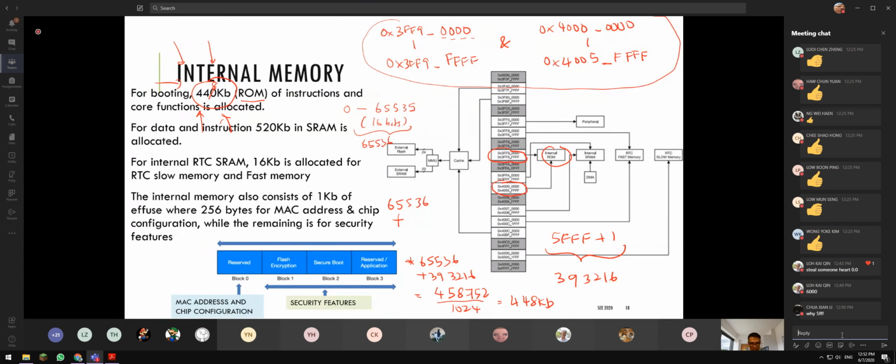Sleeping deeply doesn't mean that you are dying, or that your microprocessor is not functioning. Let's say, for example, you are sleeping at night. If you're in deep sleep, don't tell me that your brain is malfunctioning. During sleep mode, the real-time clock is still running. Sleep mode is just to reduce power consumption by disabling the main core. Remember this.